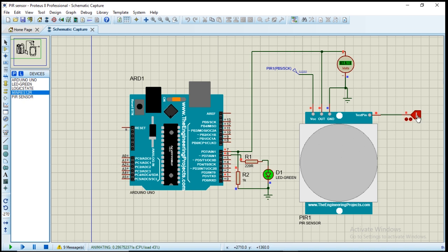If I turn this thing off, watch how it will delay for some seconds before this thing will go low. You see, I've turned it off, it is delaying. Watch the delay before the output will go down. This is how it is being produced with this Proteus simulator. Look, the signal is slow now, but it's still delaying. So whenever the delay time is reached, this output will go back to low.